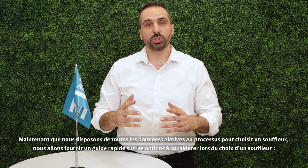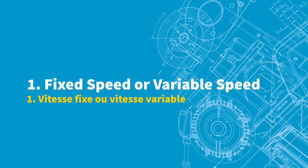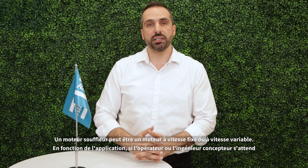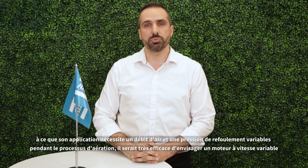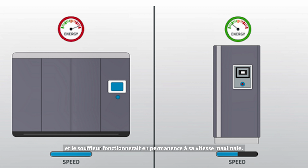Now that we have all our process data to make a blower selection, we will provide a quick guideline on the options to consider when selecting the blower. First option is fixed speed or variable speed. A blower motor can be a fixed speed or variable speed motor. Depending on the application, if the operator or design engineer expects his application to require variable airflow and discharge pressure during the aeration process, it would be very efficient to consider a variable speed motor with a variable speed drive to produce the exact amount of airflow required for his process. Otherwise, a fixed speed motor can be considered, and blower would be running at max speed all the time.